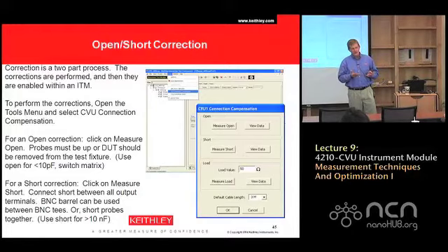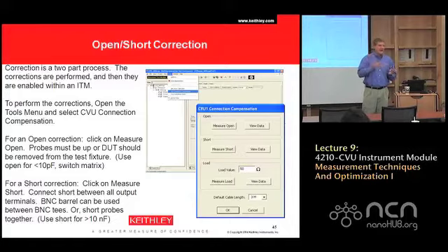Now, if you look at a traditional LCR meter, which might have thousands of frequencies per decade, it goes in and corrects only 5 or 6 or 10 per decade, and then interpolates the rest of them. And we actually have some examples, over the years, where we saw interpolation errors in the measurement.